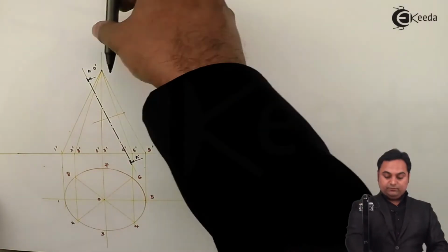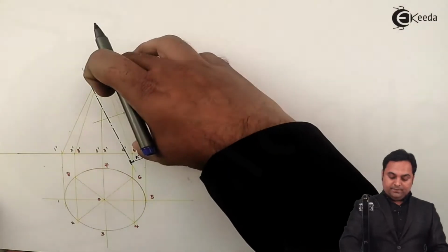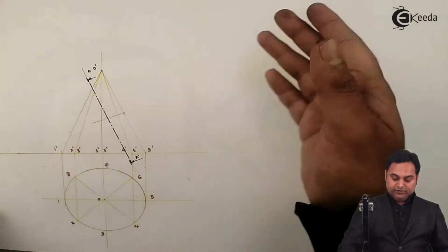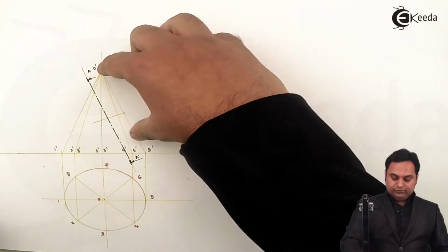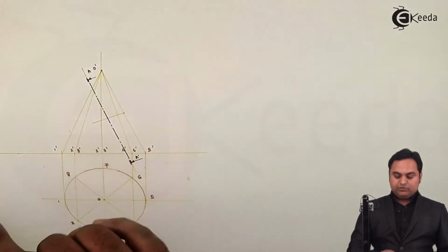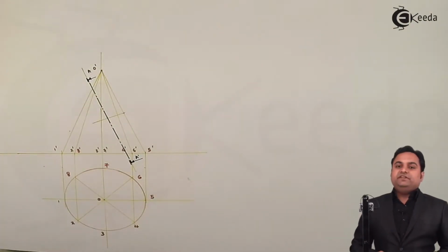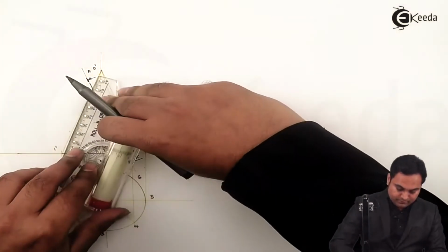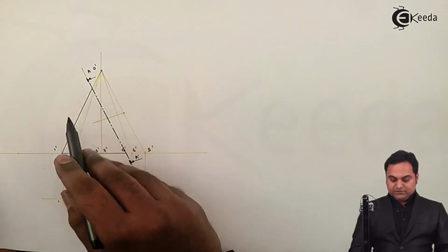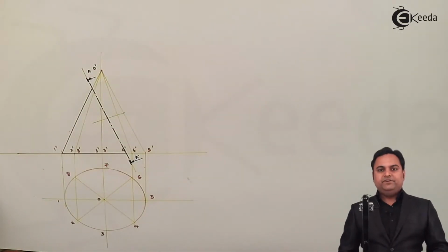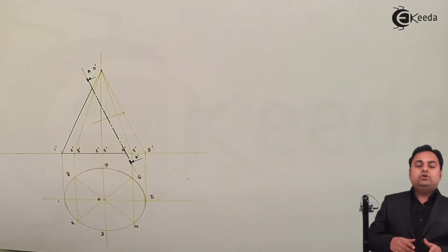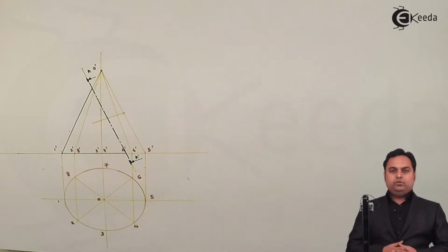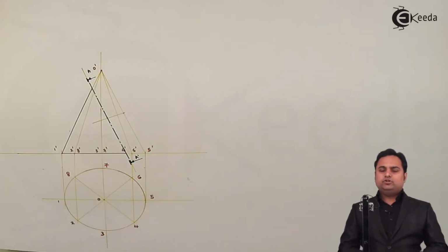Now when we are looking from top as an observer, the part which is close to the observer should be removed so that we can see the section. It means whatever portion is there at the top closer to the observer, this will be removed and the bottom portion will be retained. So the part which is retained, I'll make it dark first. So this much bottom portion of the cone has been retained, and here the cone has been cut. So a cut cone is also called as the truncated cone. So this is the truncated cone, and here we have to draw the sectional top view as well.